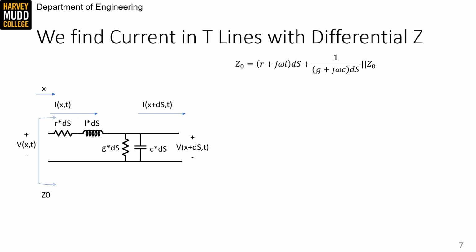As a side note, we're assuming constant values of R, L, G, and C across the transmission line in this derivation. That's a safe assumption for most modern transmission lines, but some people violate that assumption on purpose to build microwave devices. It's also a property that sets transmission lines apart from random wires on a breadboard.